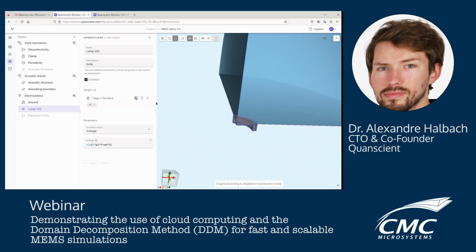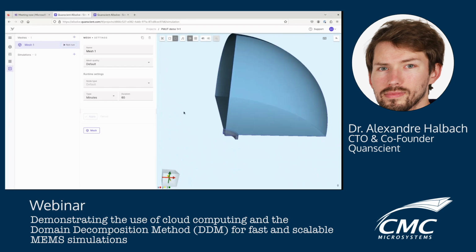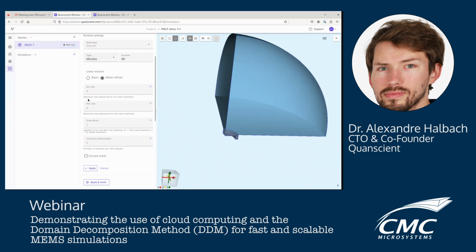So we're all set, and we can move on to the simulation section, for which I'm going to create a mesh. Now, I cannot necessarily use the defaults. I want to be able to guarantee that I capture the waves with a fine enough mesh for the max frequency I want to set up. Typically 5 cells per wavelength will be accurate in this software with second order acoustic interpolation.